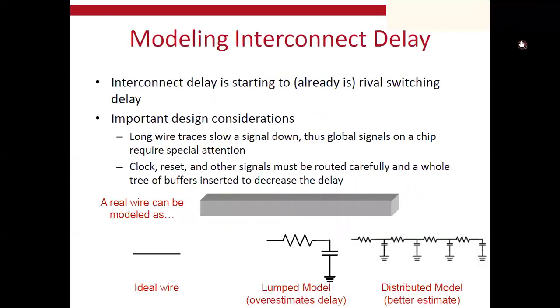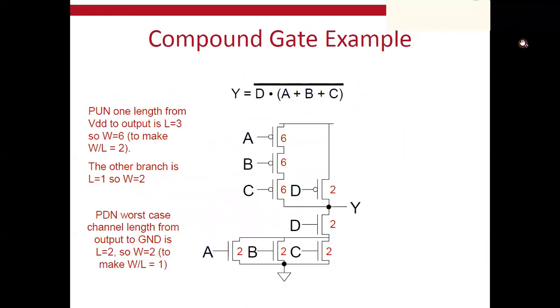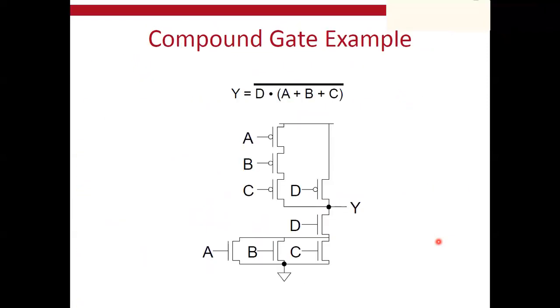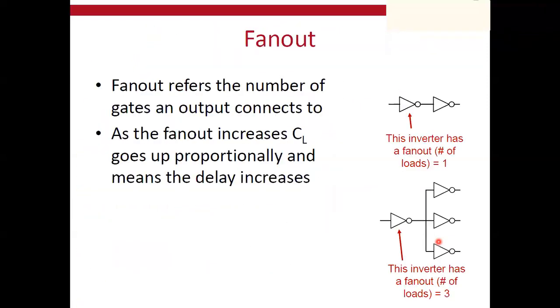Simply, if you go to this, again, critical slide here, ideally speaking, this signal should go directly to low in this stage. So due to this propagation delay, some additional power is consumed by the circuit that should not be consumed. So this is what we can call dynamic power.